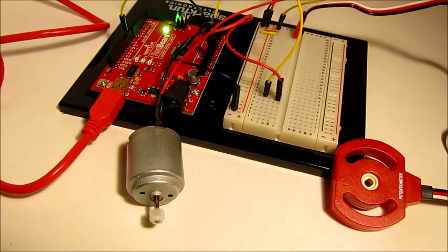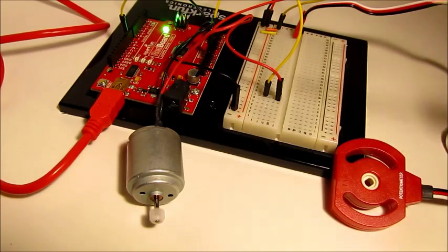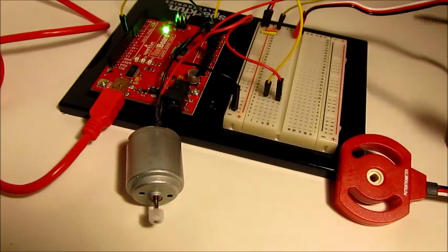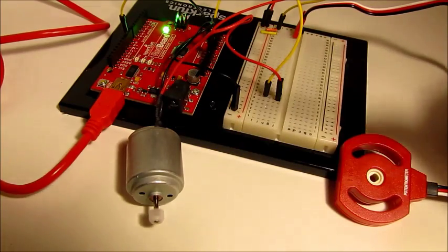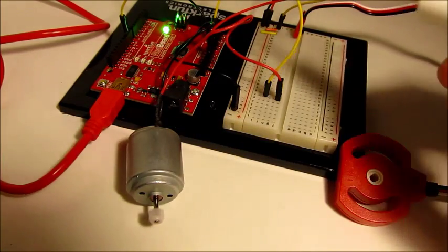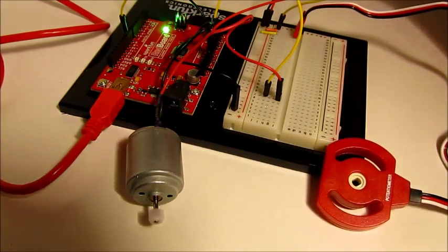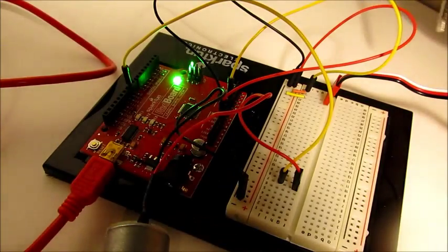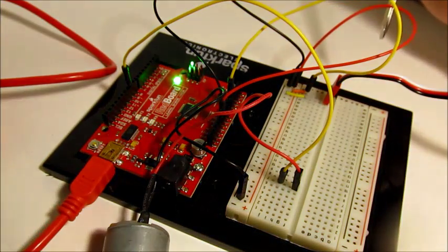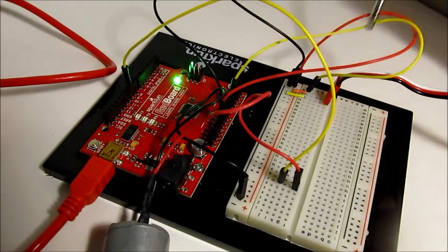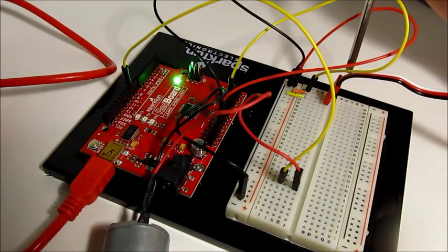This is objective number 2, where we are using a potentiometer to control the speed of a motor, using the potentiometer to control the voltage output coming from the Arduino to the motor. The way this works is the power and ground are supplied by the Arduino to the power bus, which the motor and the potentiometer are both connected to.